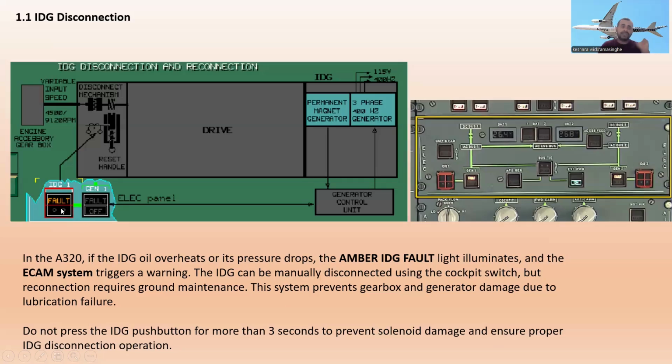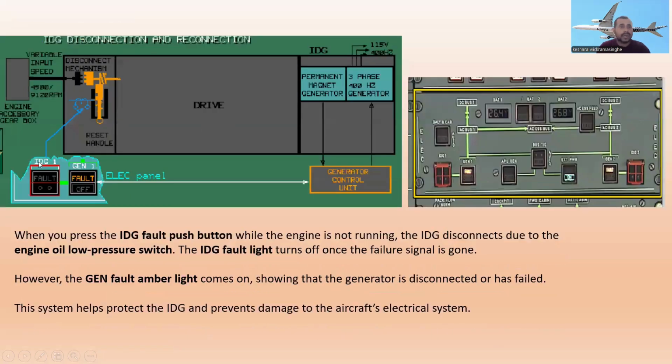Now in this slide, I press the IDG push button. In this situation, when you press the IDG push button while the engine is not running, the IDG does not disconnect, due to the engine oil low pressure switch.